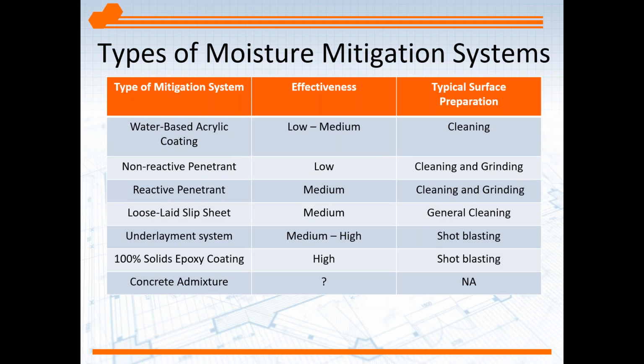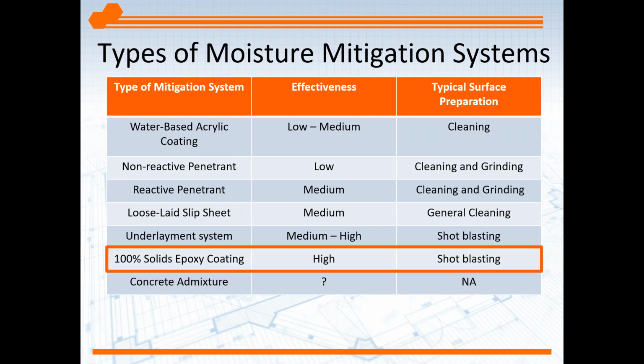There's different ways to mitigate moisture. I'm not really going to go pro and con with any of these methods here, but most popular, if you will, is the 100% solids epoxy coating. And I say popular just because it has a good track record. But also important, its formulation and performance are governed by ASTM standards.